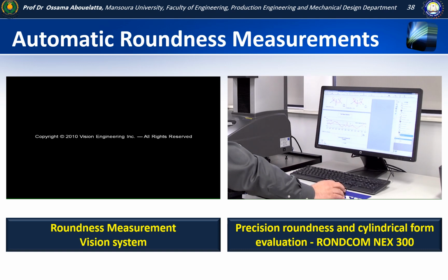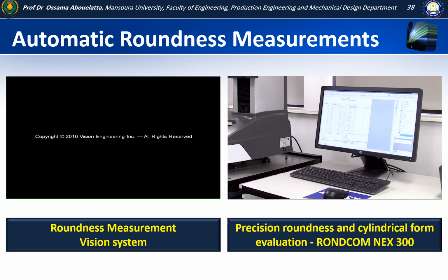And from here, we will also measure coaxiality at a couple of different points and be able to do that in the report all at once. Also, from our two traces that we took across the cone with R-axis tracking, we were able to evaluate straightness on both sides of it. And we were also able to compare those two straightnesses for a taper, where, in this case, we show an included taper of almost 37 degrees.